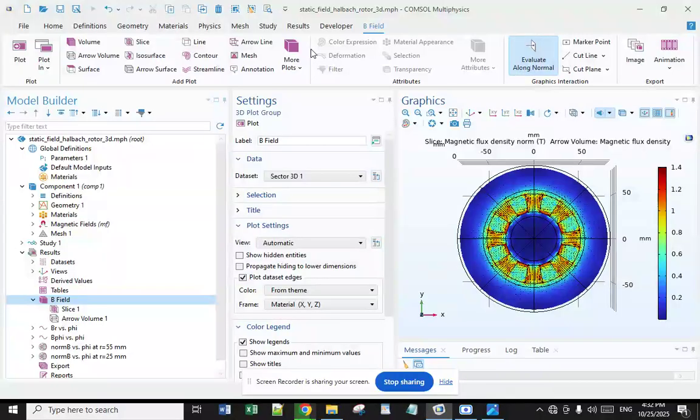Of course, the idealized case of infinite length is not realizable, and in practice, the finite length of the cylinders produces end effects, which introduce non-uniformities in the field. The difficulty of manufacturing a cylinder with a continuously varying magnetization also usually leads to the design being broken into segments. And what about the applications?